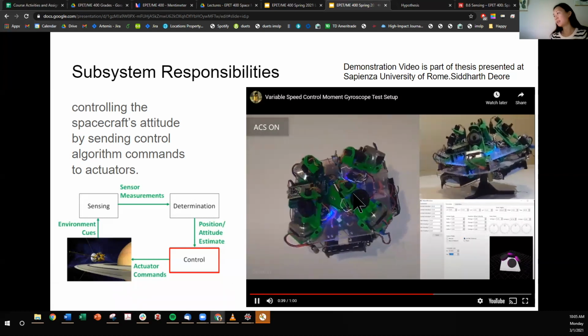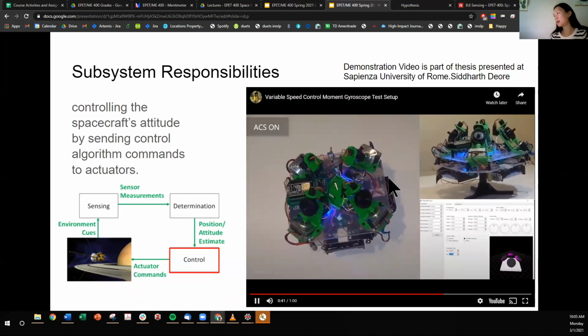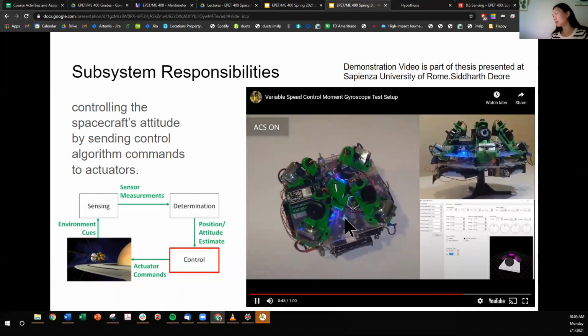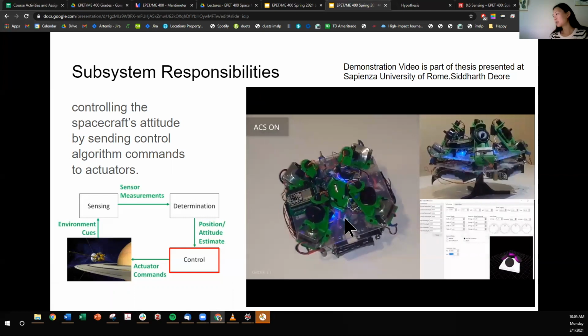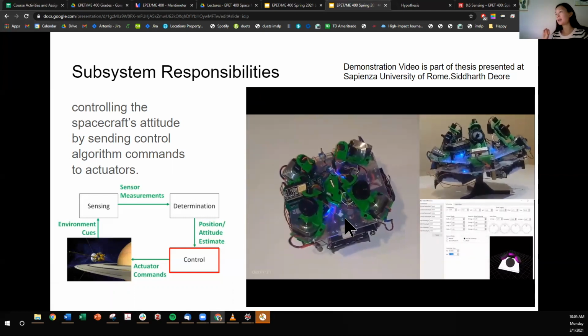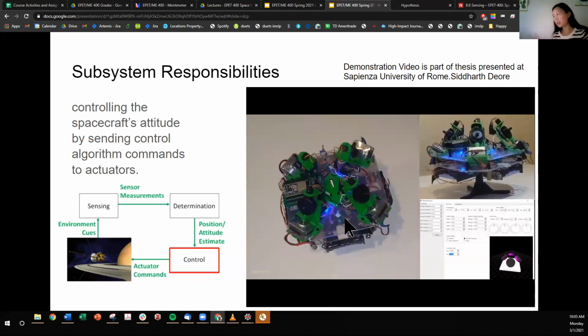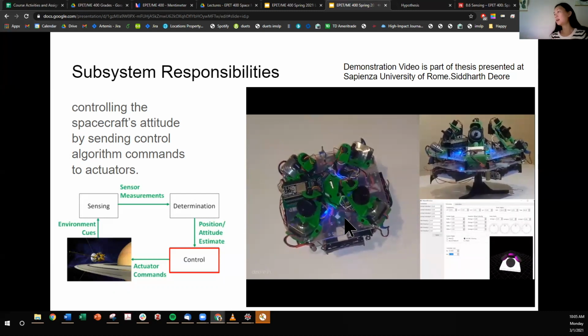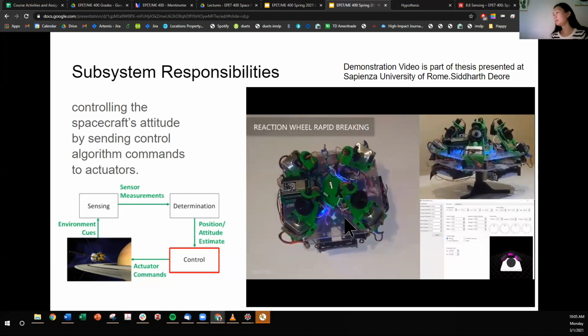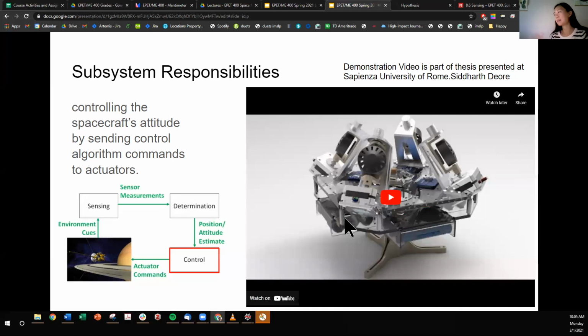Do you see that click in? So there are much less oscillations between when the disturbance happens and its steady state. So a control system takes in measurements, figures out how to compensate the system so that it either stabilizes or tracks a trajectory, something desired, and cleverly dampens out that kind of oscillation.